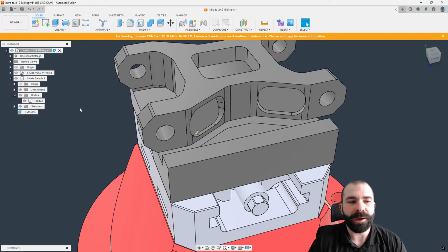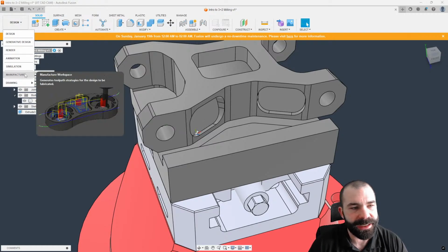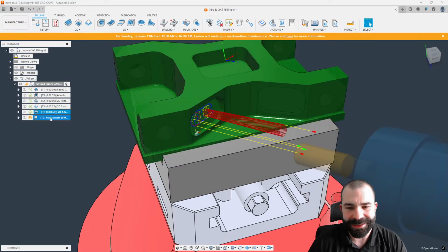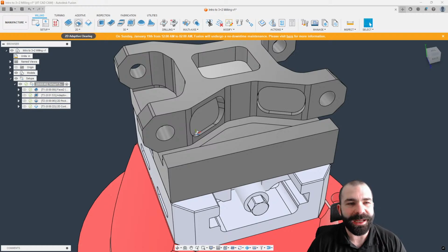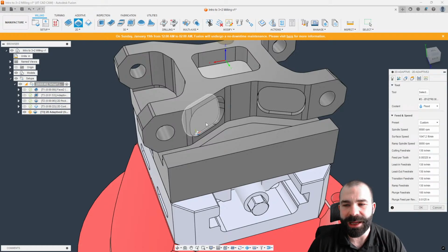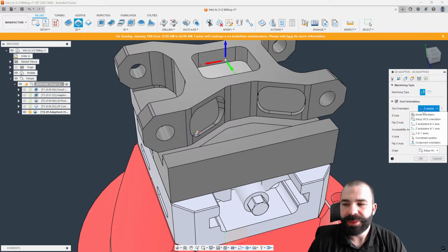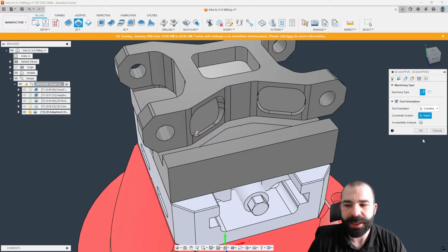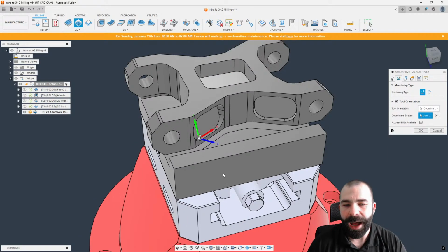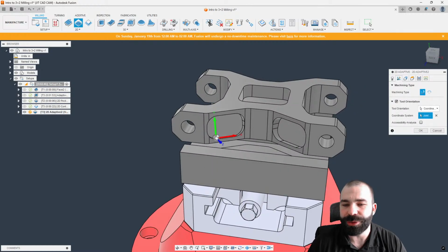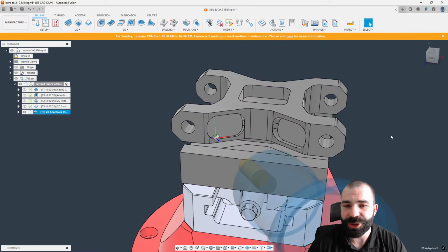So when it comes to tool pathing now, this is going to be the cool thing, right? We're going to go ahead and delete these tool paths. But if I went in, again, traditional approach, 2D adaptive clearing on this pocket, I go back to tool orientation, there's an option here to pick a coordinate system. Now, I can pick that joint origin. As you can see, my X and Z are automatically orientated to that joint origin.